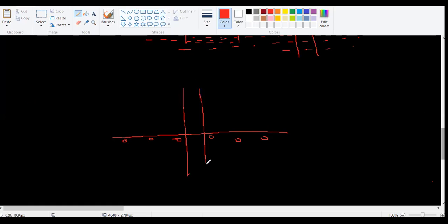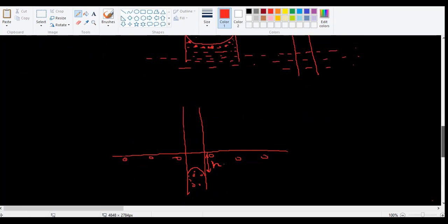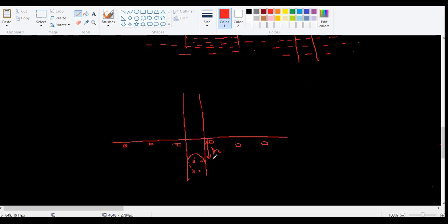If I put a capillary tube here, the level is not going to rise this way. Instead, the level is going to drop like this. This is a very, very interesting situation. The reason is very simple: water and glass like each other, but mercury and glass do not, because the adhesive forces are less. This is what we'll take as height, the capillary rise. Here you would call it capillary rise, which is negative, or you can say capillary drop. So this is for mercury.